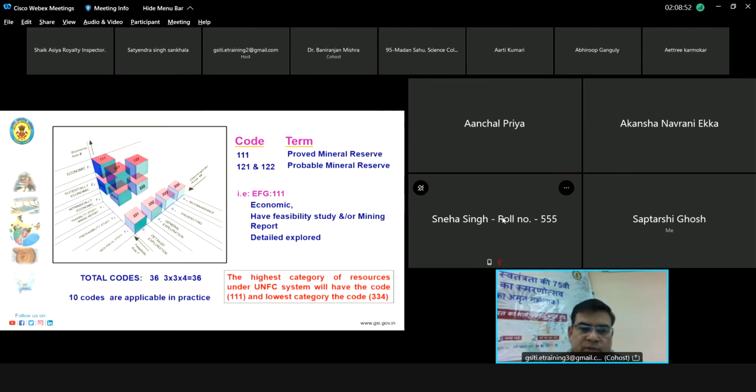Now these are in three-dimensional form. This is the geological axis. Here it is G4, the economic survey, the preliminary one. Then prospecting in G3, then general exploration in G2, and detailed exploration in G1. All these explorations increase your database and your confidence. Because in borehole planning, we can make a scout borehole, then there is some specified borehole spacing in G3, and again it is reduced in G2 and again in G1.